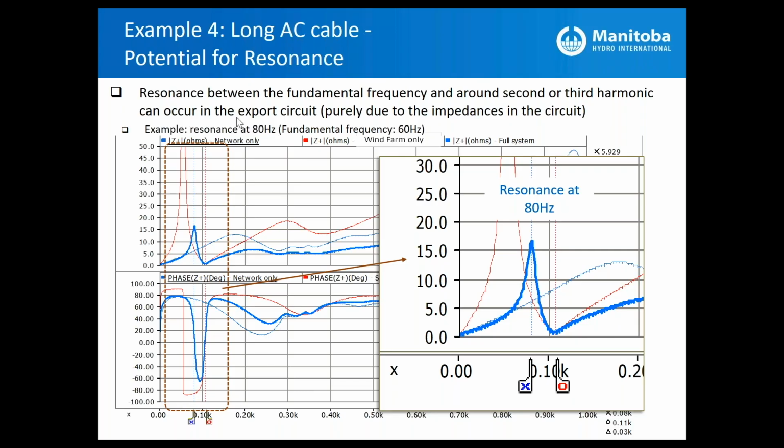observed that the turbines were issuing over frequency trips after some of the faults we tested. And after further analysis, fortunately this was during feasibility studies. So during the design studies, this is what we found, and they had to ask the vendor to make some changes in their controls or tune their PLLs and prevent that. But what was happening was the overall frequency, the impedance characteristics.